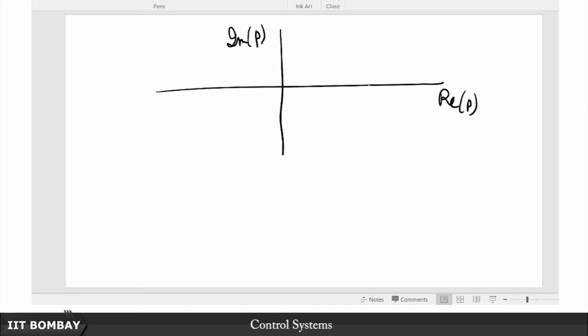Now suppose you have a violation of the interlacing property. That means that after encountering a 0 of the imaginary part, you encounter the next 0 of the imaginary part here, or maybe here, without first encountering a 0 of the real part somewhere on the imaginary axis. So these two violate interlacing.